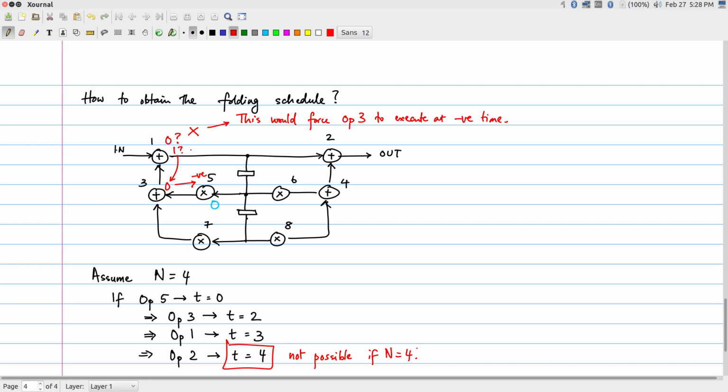In fact, this is raising a fundamental problem for us, because if I really look at it, there is a path that leads over here which has a total delay length of 2 plus 1 plus 1 plus 1, 5 time units. So there is fundamentally no way that I can get everything to finish within 4 clock cycles with this arrangement.